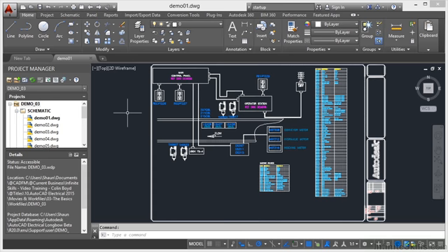Now, I might not want to open up new drawings that way just by selecting a template. I might want to utilize a slightly more sophisticated tool that's been around for a long time, and that's your startup dialog box. Now it's controlled by the startup variable. So make sure down on the status bar you've got your dynamic input on. Bring your crosshair into the drawing area and type startup, all one word. So there's startup there.